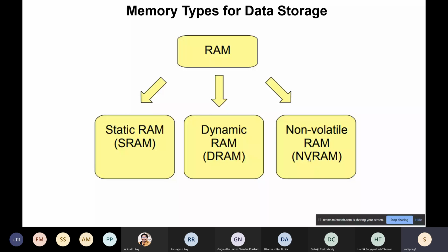Some magnetic nanoparticles are used inside the RAM memory architecture that get magnetically polarized, and that results in non-volatile data retention. That means after powering off, your RAM will still store the data, and if you power it up again next time, you can retrieve the old data, which was not possible with DRAM and SRAM. So NVRAM virtually provides infinite write and erase cycles as supported by SRAM and DRAM, but it also retains data even if power is off.